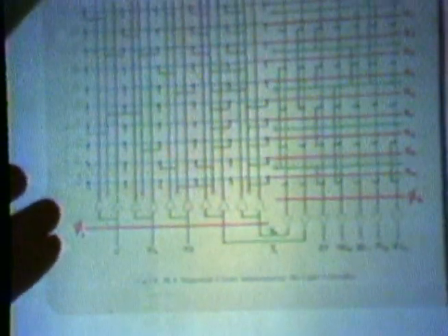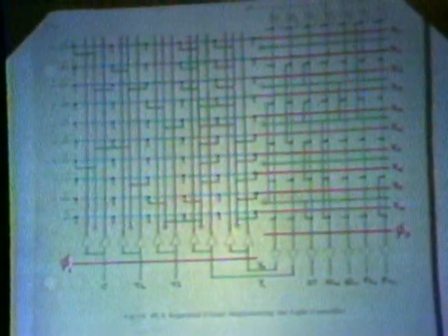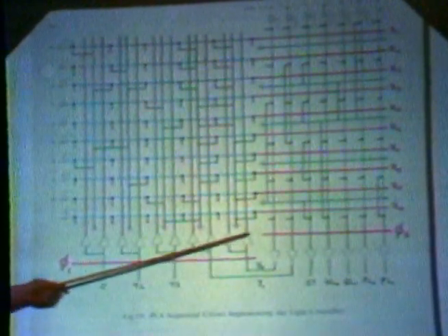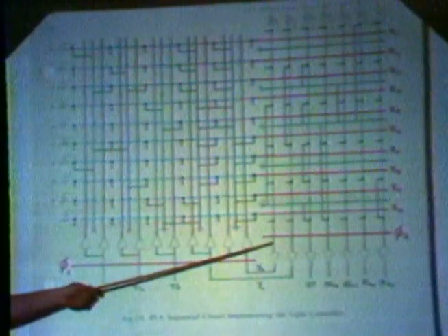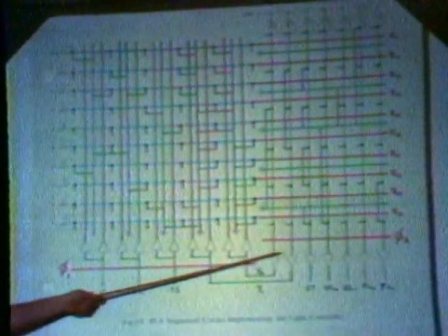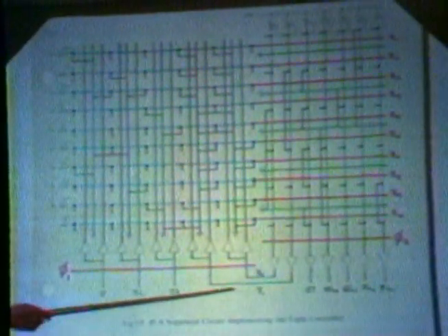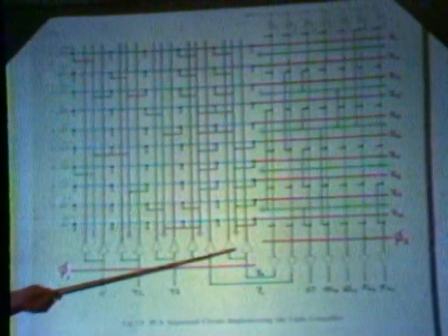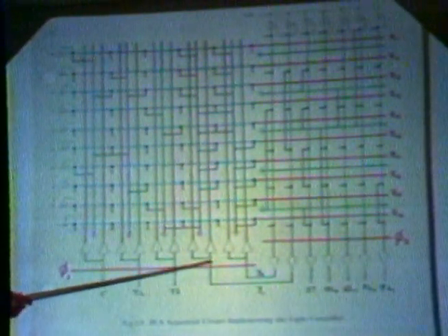Let's just push the state table off. The 2 outputs, Y0 and Y1 of the PLA, which have already been gated by the phase 2 clock line into this output half register, are then fed back underneath the phase 1 clock line into this set of inverters as an input half register.